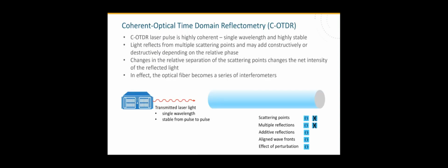How do these disturbances happen at a very low level? So the laser light is transmitted into the fiber optic cable, represented here. And in that fiber optic cable, even though it's super pure, very low attenuation, there are still imperfections in that fiber optic cable that create reflections back to the source. These imperfections come from minor changes in the density of the glass, minor changes in the reflective coefficient of reflection of the glass. And anyway, so there's lots of these points. And from every point, there'll be a tiny amount of reflected light going back to the source.